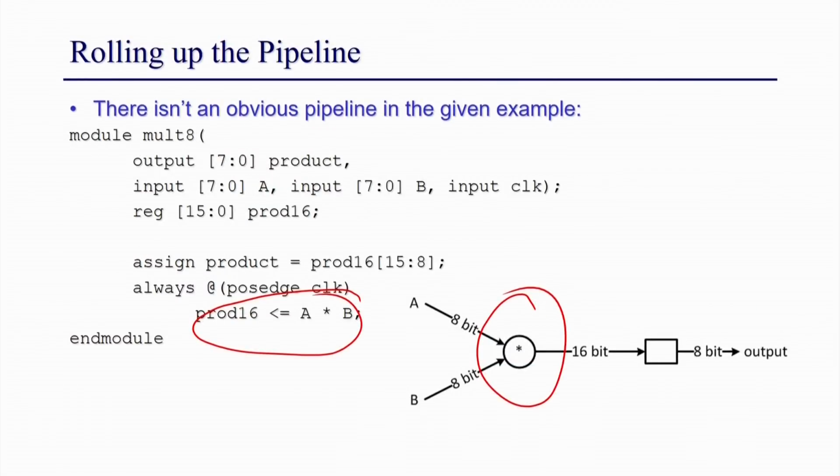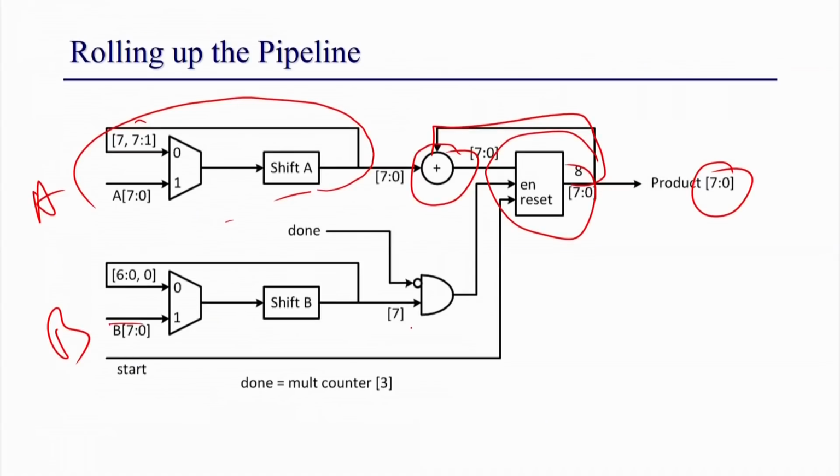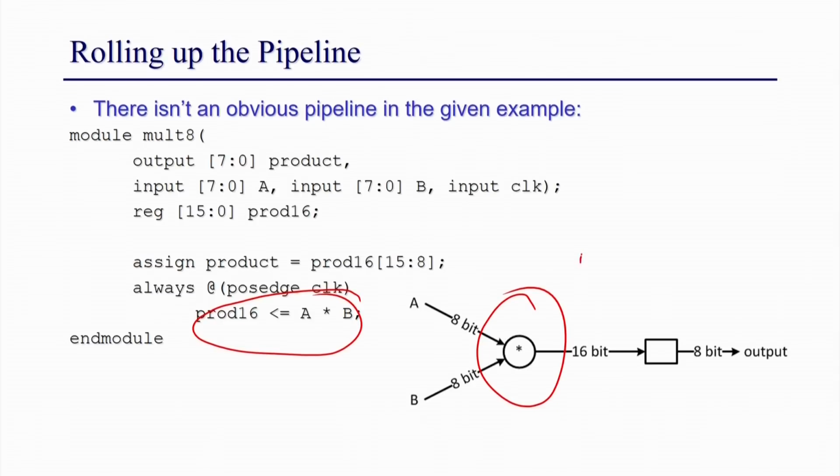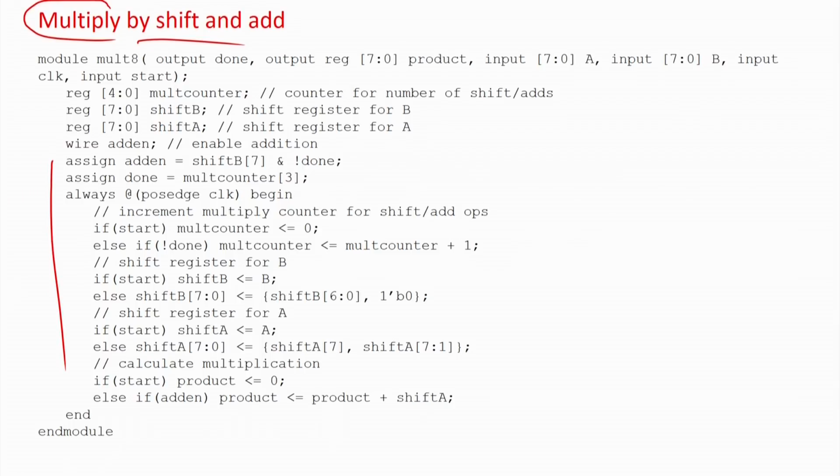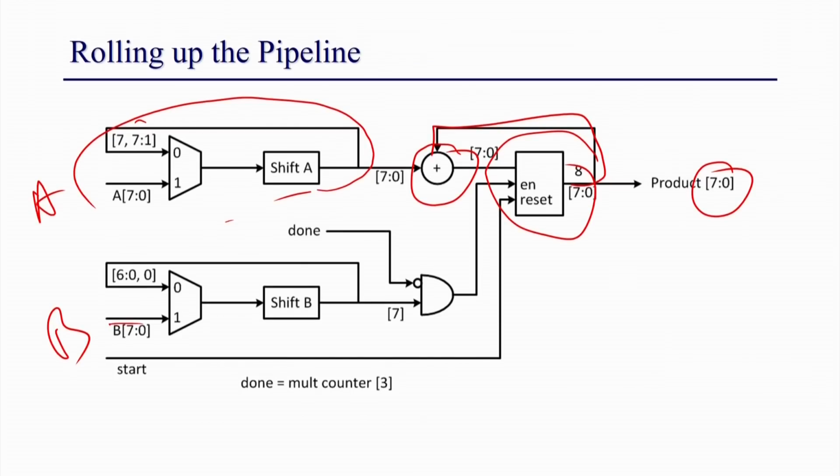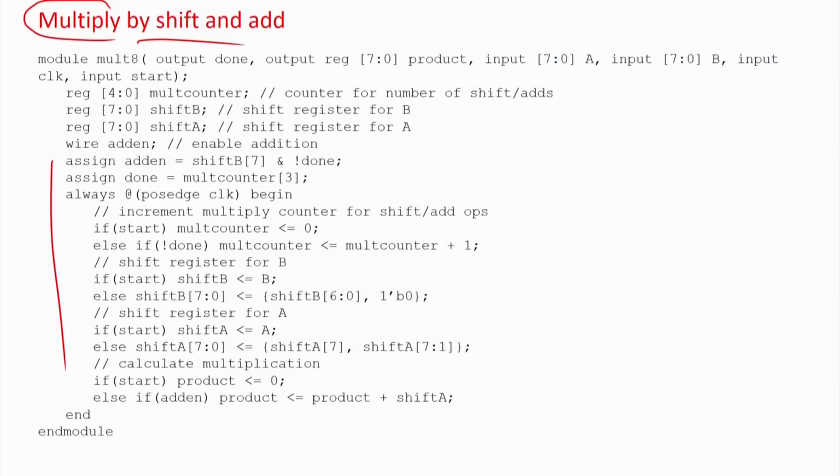But you can see that I can replace that big multiplier by a simple adder. So it will give you a big area benefit, but it basically becomes a pipelined iterative version. It will take 8 cycles, whereas the multiplier takes only 1 cycle. I am just repeating the same statement: that is also a design choice. If you want to achieve as low an area as possible and your latency does not matter, then you can replace this multiplier by a simpler shift-and-add multiplier, which will take 8 cycles. So your latency will become 8, whereas your latency here is 1.